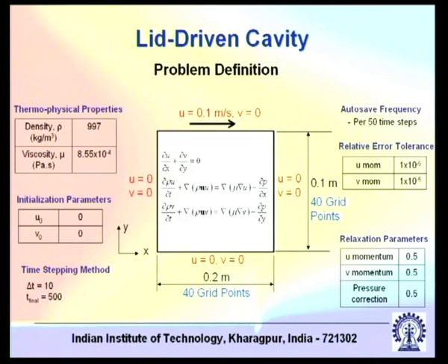So there is a relationship between the nature of meshing and the nature of the algebraic equations that get generated out of it. If there is a variable meshing, one has to have it graded: a refined mesh at locations where you want to capture strong gradients, and a coarser mesh where you do not want to capture such strong gradients.